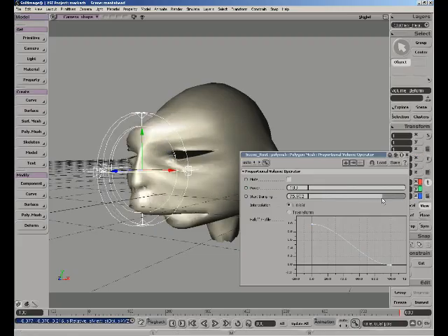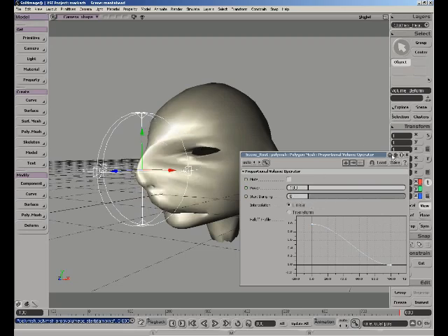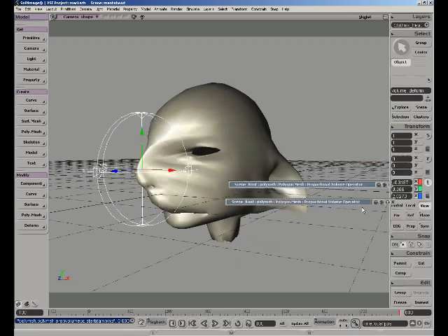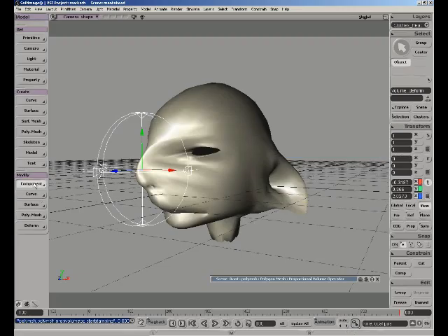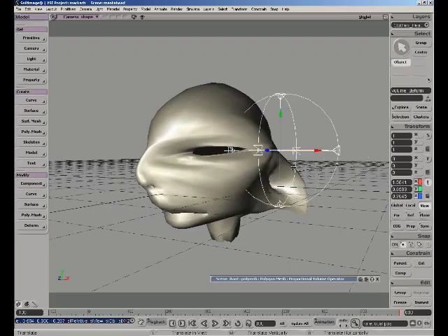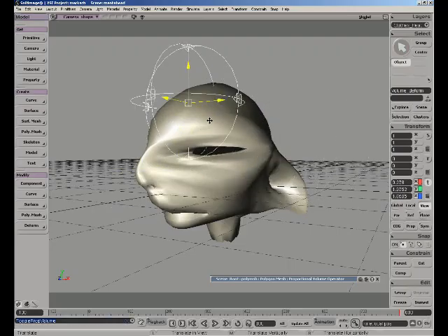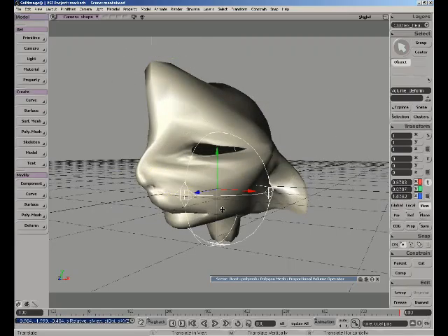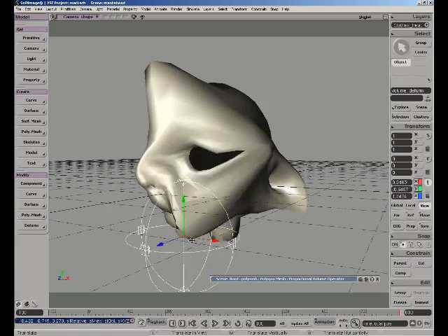If I pull this out, you can see how that works, like this. And lastly, you can quickly hook up and unhook the deformer by going into your component there, and you can see it's Shift V, or just click this. So I'll first click it, and I'll move this over here, press Shift V again, and now I can move that. So you can see it makes a very quick sculpting tool as well.